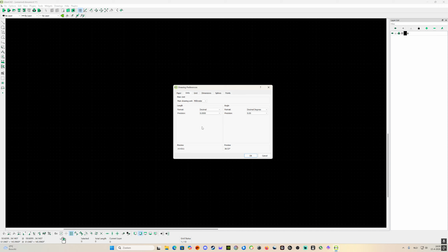Units is decimal, in millimeters because I'm European. The grid, show grid. That's also good. The grid is the little dots you see, that's the measurement of the grid. X spacing, everything is auto. Leave it. This is the most important one. Also, the paper is important. Now, general scale. That's the general drawing scale. You can leave it like this.